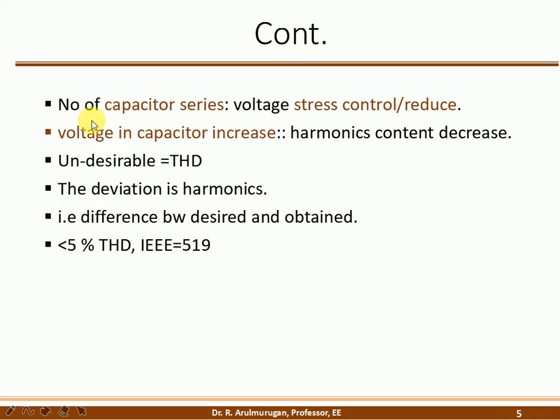Then for the first two methods, the diode clamped and the flying capacitor, you are going to use capacitors. A number of capacitors are used to control the voltage stress. How do you connect the capacitors? The capacitors are connected across the source side.